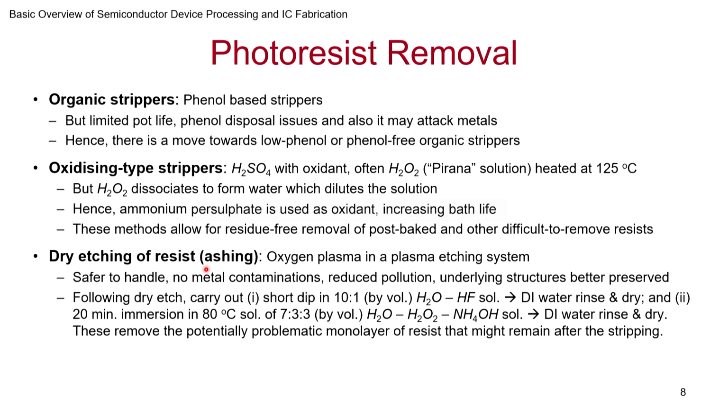So it's safer to handle, no metal contamination, comparatively less pollution, and the underlying structure is better preserved in this, because sometimes during these piranha etch and other potent etches, the other structures may get affected adversely. So that way it is better preserved.